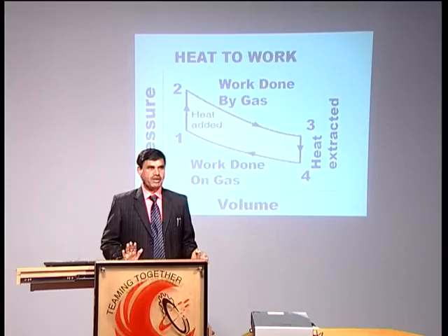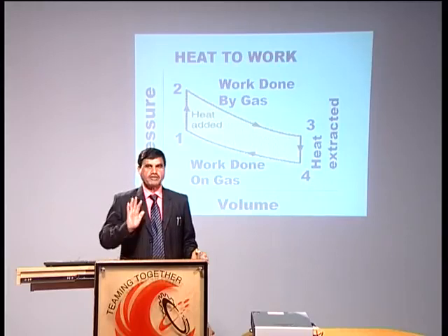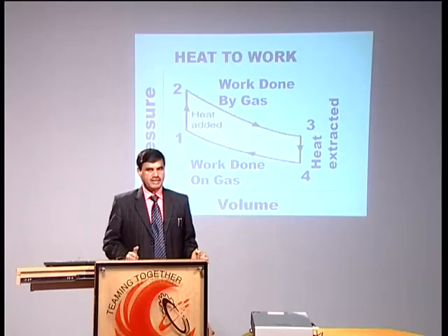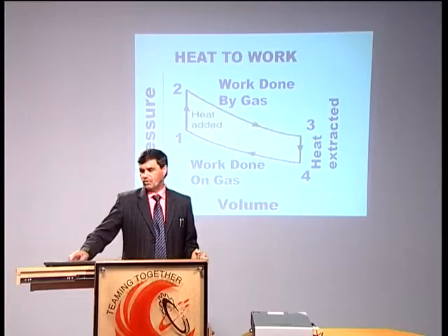Out of these three, if I am comparing, the best one is heat addition at constant temperature. Second is heat addition at constant volume, and third is heat addition at constant pressure, from the thermal efficiency point of view. When heat addition is at constant temperature, it is the Carnot cycle. When heat addition is at constant pressure, it is the Diesel cycle. When heat is added at constant volume, it is the Otto cycle.